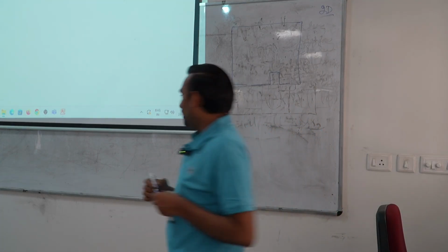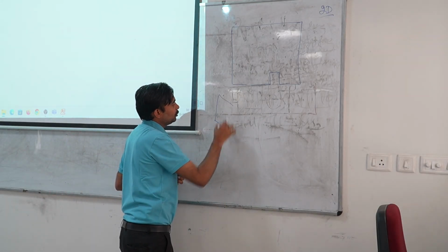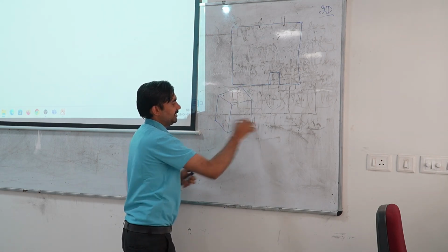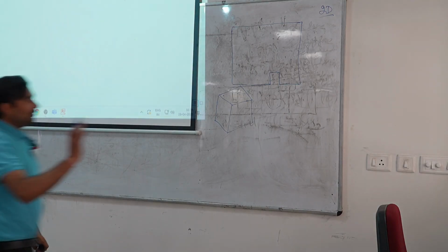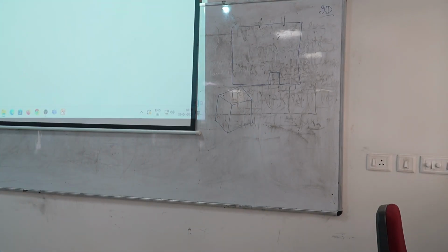In general, whenever we define the domain using blockMesh, we define hexahedra, a three-dimensional structure. Even when I use it for a 2D simulation, OpenFOAM defines hexahedra only, because the solver has to stay consistent with the files.